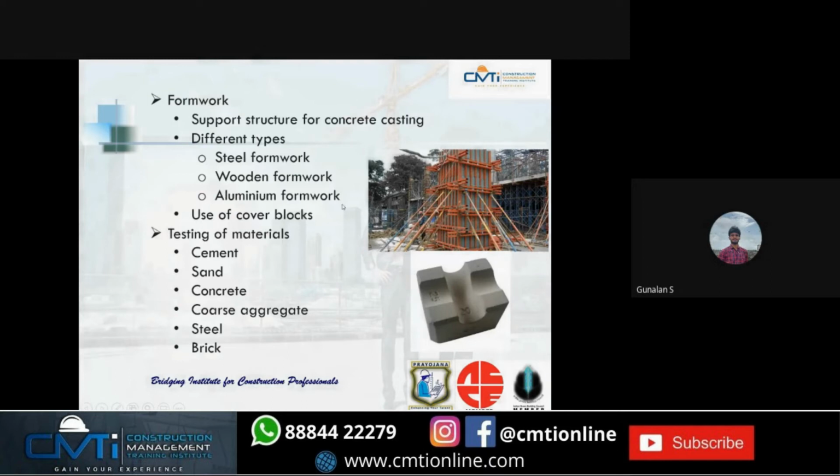Next, formwork. Formwork is a basic structure which supports and acts as a mold for the concrete. There are four types of formworks mainly. Shuttering is a formwork component which is used in vertical components. And next comes the centering. Centering is for horizontal components like beams and slab.